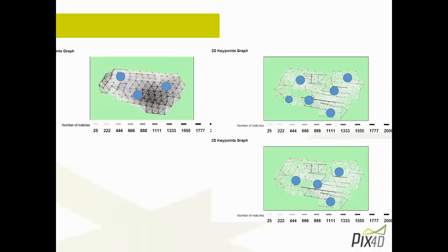And I would recommend 2 ways of setting the ground control points in this project: either by treating the 2 subparts as individual and including ground control points in one subpart and the other, or to try to put the ground control points in the part where there was very little match, to try to help the software to improve and to avoid this error accumulation at this place. Now, having said that, this is still not ideal.